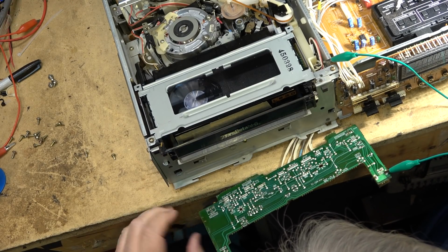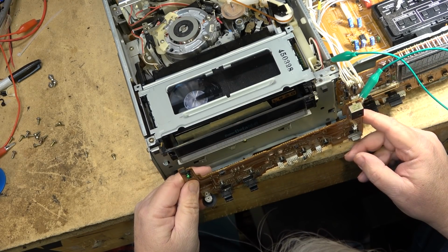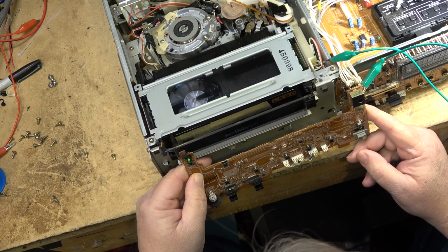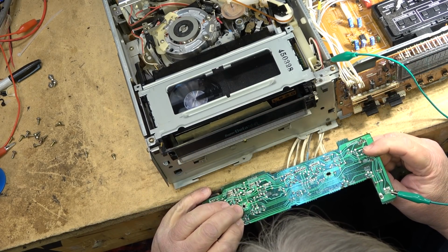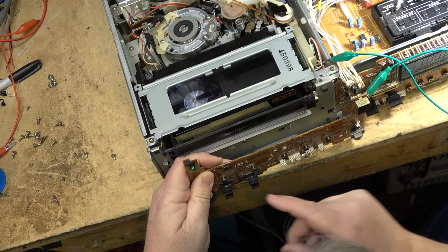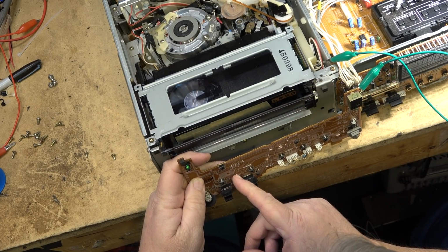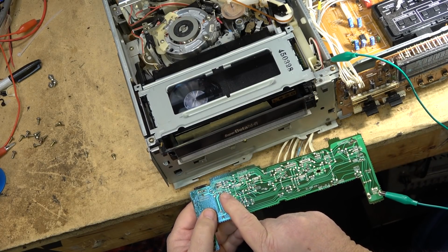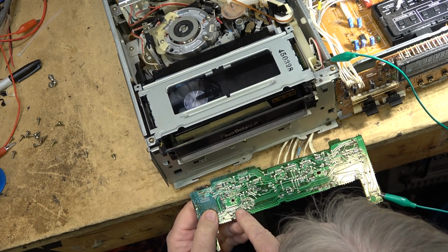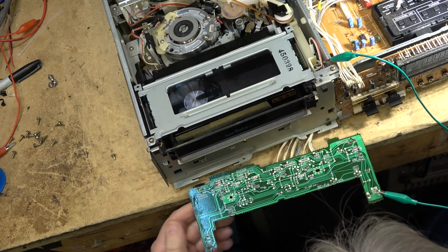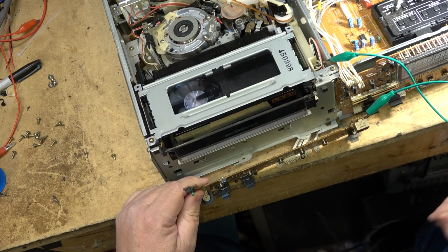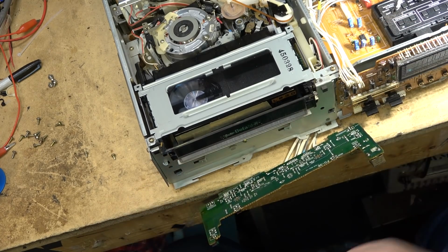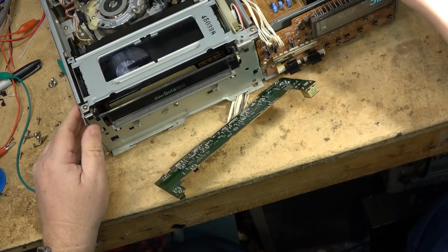This unit is obviously using a resistor divider network to control the modes, and it looks like it's this resistor right here. If we look at the trace, that trace comes up to here. So the trace from here goes up to this jumper, and then it goes through that resistor. And that resistor is changing the resistance being sent to the system control IC, which is measuring the resistance and giving me an inaccurate read. So let's pull the switch out and see if we can fix it.